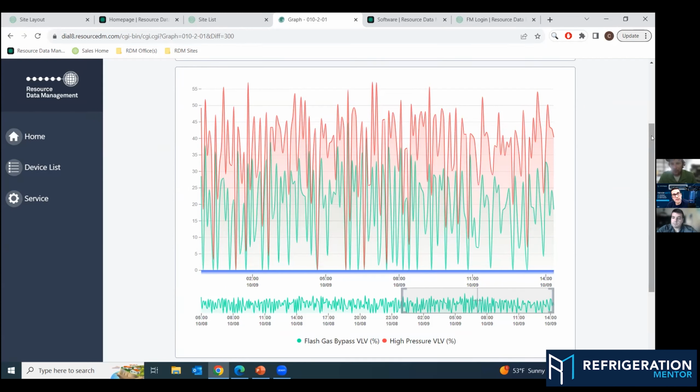Another thing I would definitely check is, was this set up in the middle of the summer? Was it also checked in the middle of the winter? Because they're going to run differently. That's where the fine tuning needs to happen with these things, because you set it up the first time when it's really warm out. We can do our best to simulate what is going to happen in the wintertime, or vice versa in the summertime, but you've got to go in and check these CO2 stores in those times. Oh yeah, 100%. They're going to run different.